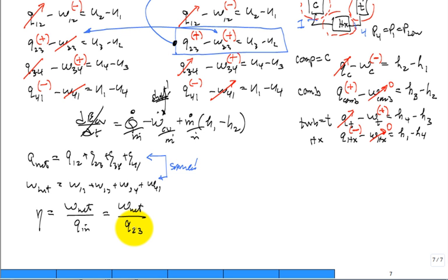And there's a mean effective pressure. I'm not a big fan of this metric. Maybe they'll make a big deal of it when they do Thermo 2 next semester with you. But it's the net work of the cycle divided by the displacement volume. Well, what's that? It's the difference between the initial volume, V1, and the final volume, V2. So it's V1 minus V2. That's the displacement volume.